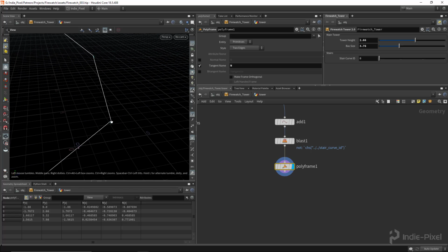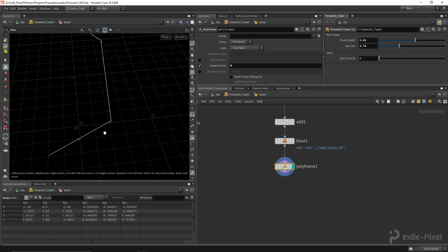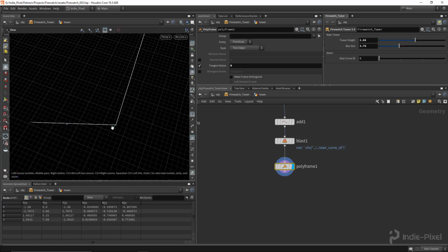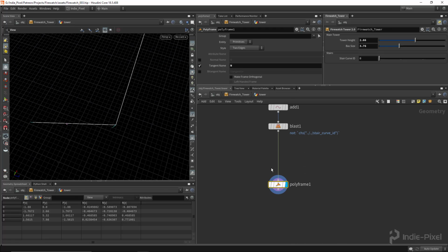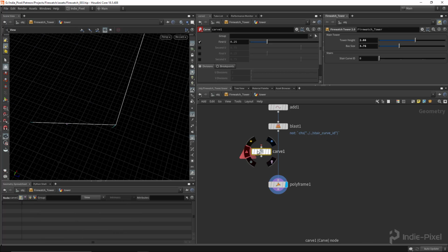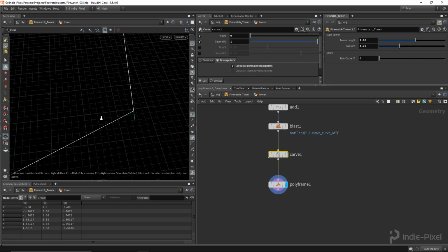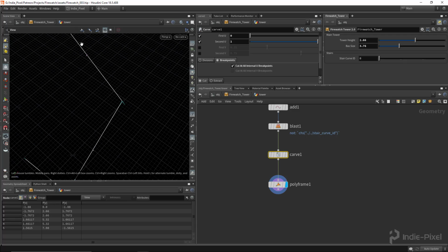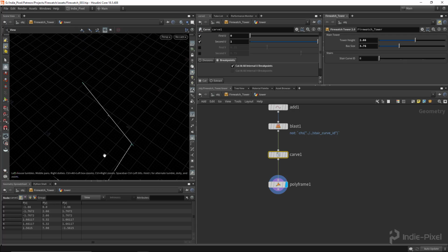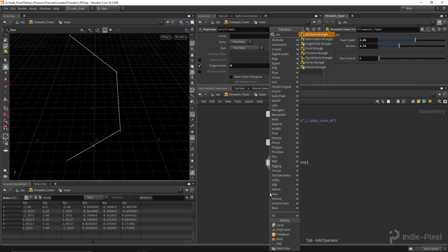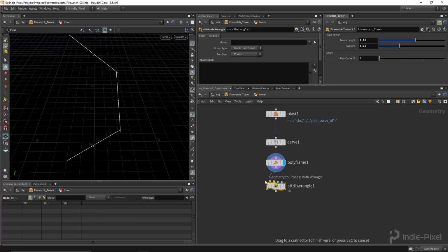And actually, now that I see this, we need to break it up because I don't want these particular normals to be the average direction there. So if you remember, we can drop down a carve node here, and we'll just break it at all internal U breakpoints. There you go. So now you can see the difference, right? We're getting the perfect 90-degree turns there for our normals. Beautiful. All right, so to create the other direction, we need our right and our up directions.